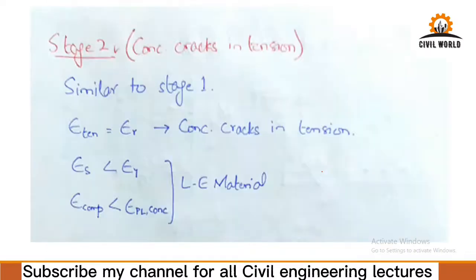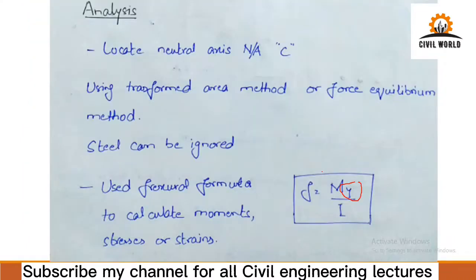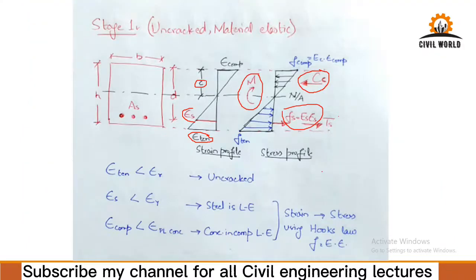Okay, so then coming to stage two, which is the point where concrete cracks. It is similar to stage one. The only difference is that now concrete has cracked and stresses are not taken by the concrete, because the concrete section is already a cracked section. So this stress portion taken by the concrete